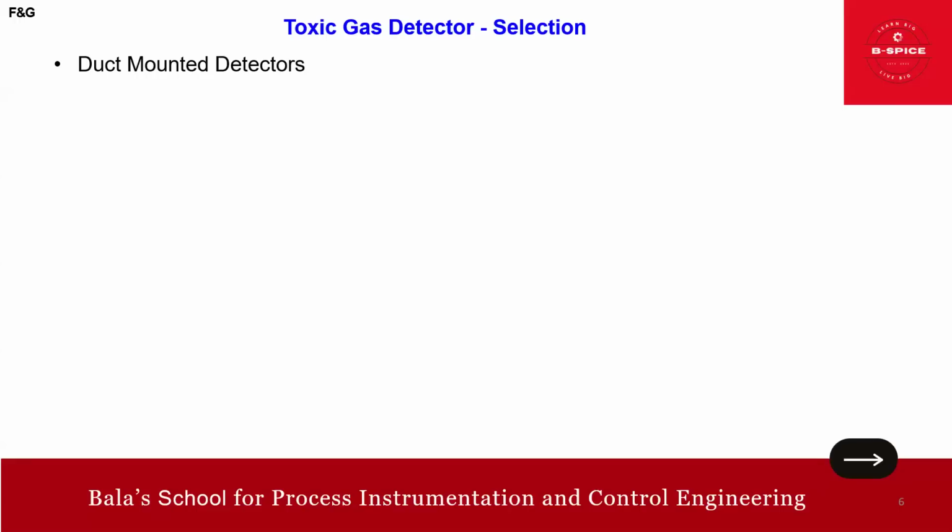So the gas detector shall be provided complete with all mounting accessories for duct mounting, ensuring a leak tight installation. That's it. And also the sampling in a high airflow environment. And additionally, the detector shall be easily removable from the duct to facilitate the maintenance. That also needs to be enforced.